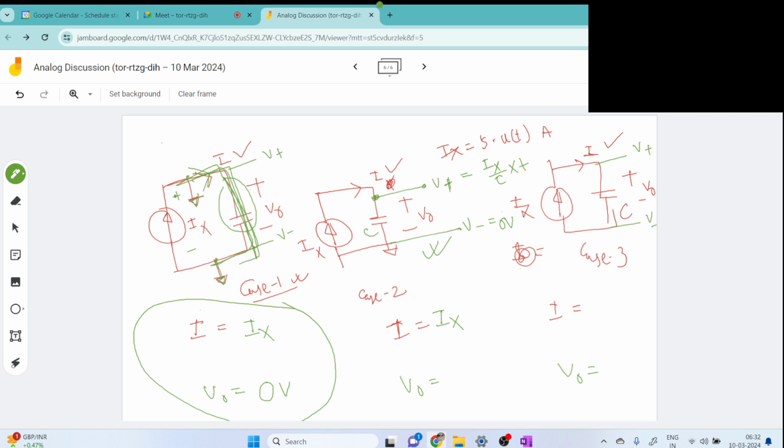As the current is constant, it will be outside of the integration, and here we have only the integration of dt, that is nothing but t. We could use t1 to t2 as well if you want to, but whatever the time is, that is t. We are assuming that it starts from t equals 0, so we are not writing t1 and t2.